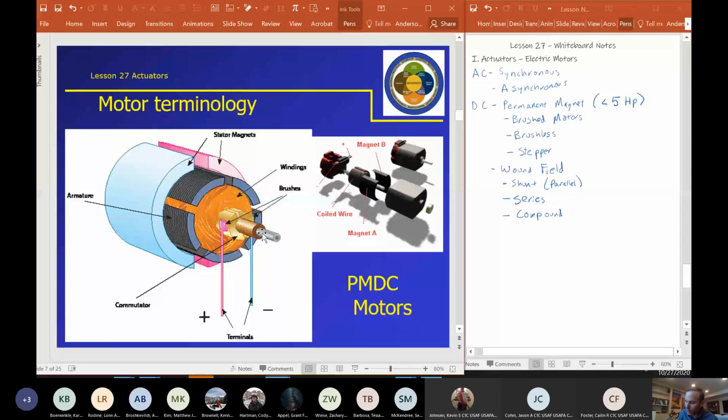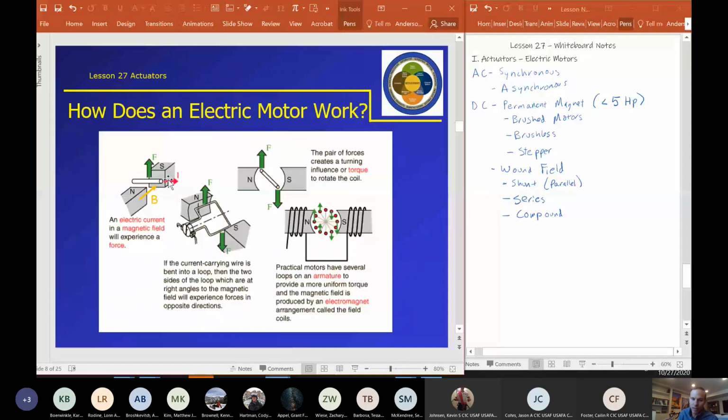The right-hand rule tells us that, if you put your fingers in the direction of the red arrow of the current, and then curl your fingers in the direction of the yellow magnetic field line, the thumb will tell you which way the force is generated. So a force would be generated that would tend to push that wire upward.